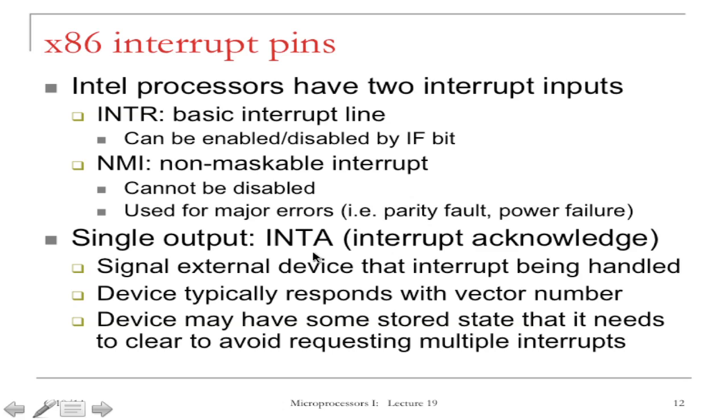Once the device sends an interrupt by raising this INTR pin, it will expect to get this INTA from the microprocessor, and once it sees this INTA is asserted, it will stop asserting this INTR. Because if you keep asserting the INTR pin, the processor is going to keep responding to the event. So it's kind of a handshaking between the microprocessor and the external device.